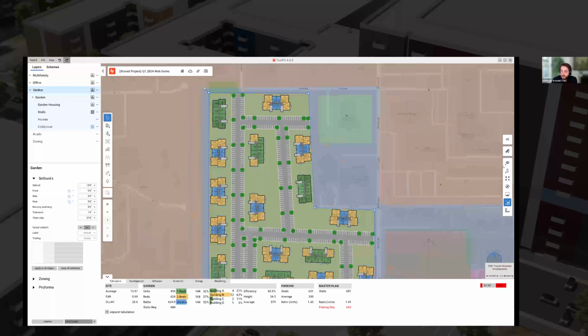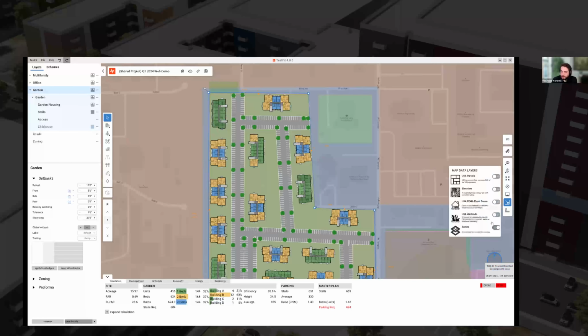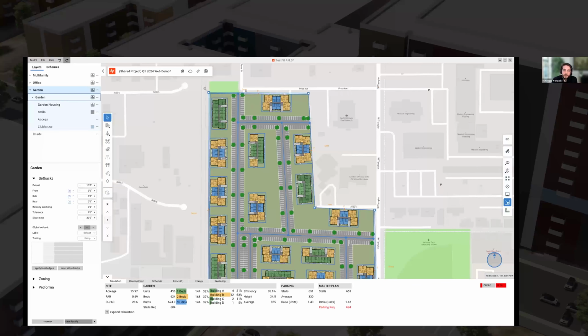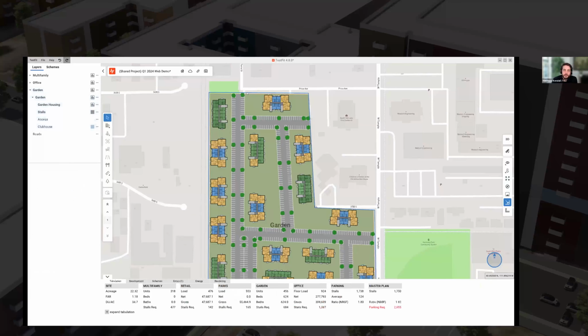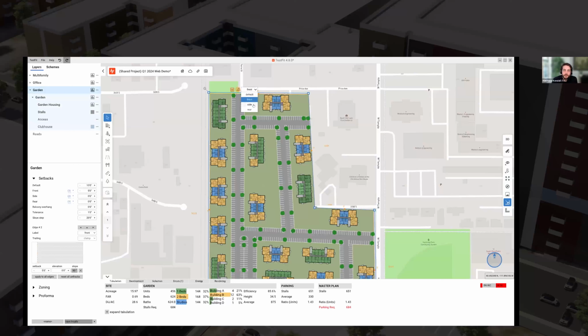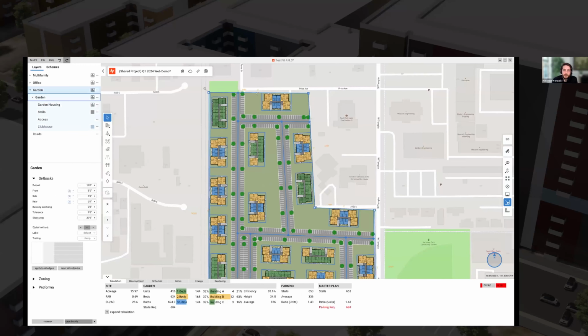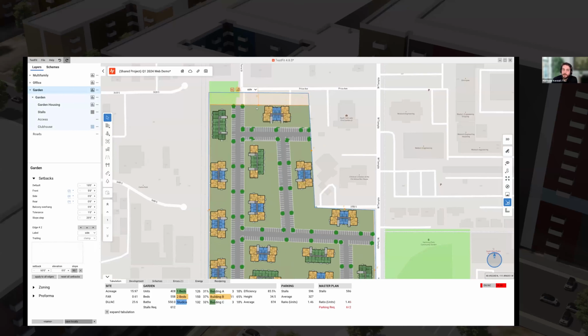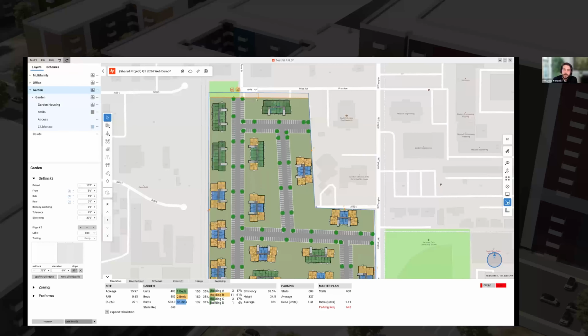So now, and I'm going to just turn off our background image for right now, we can actually see we have two frontages over here. This one, I'm actually just going to change it back to a side. So now it's gone back to our 0 setback because that is required. You still have the ability to change that as needed. So I'm just left clicking and dragging on that setback.